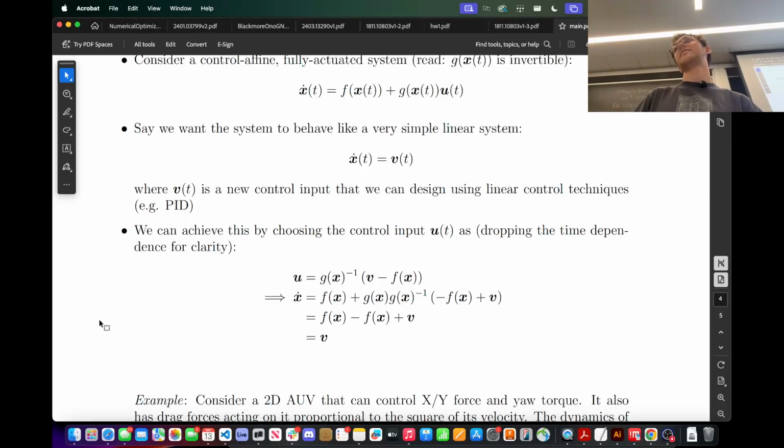Yeah. Do you have a separate, like, do you have controls for the mechanical arm for the objects? Yes, those are even more simple than this. Usually there's a servo that has a position set point, and the servo firmware probably has an internal position controller. It's using PID on the inside, I'm sure. But all we have to do is send a position set point to a servo, and it's going to go there and probably do what we want it to do.